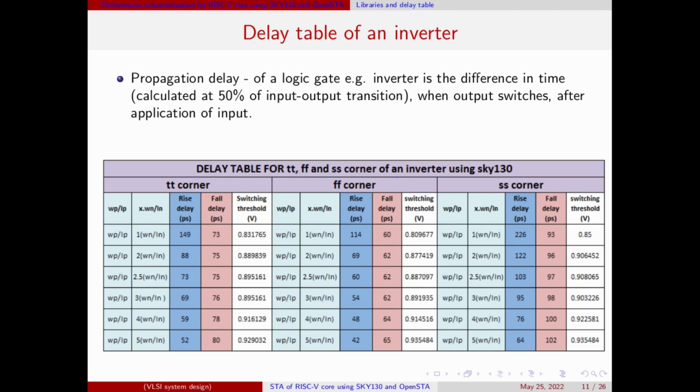This basically answers why we need to do static timing analysis across the different PVT corners. Meeting the design specification across the different PVT corners ensures that the functionality of the design will be met after the fabrication of the given design.